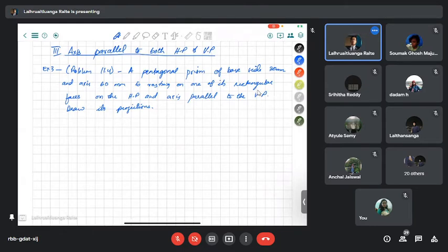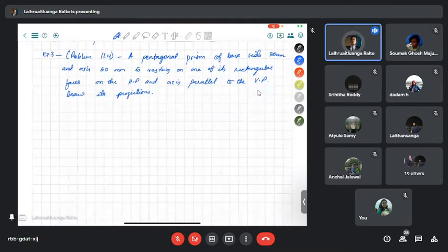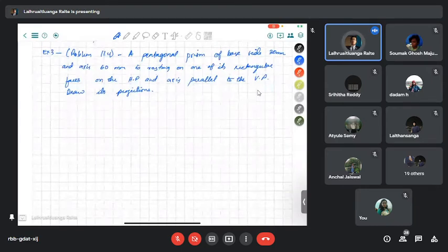Okay. So here we have a condition wherein the axis of that prism is parallel to the VP, and when it is parallel to the VP, it is perpendicular to the profile plane. So that is why we need a profile plane for this particular drafting. The profile plane is where the profile of this solid is going to be projected, which will be the pentagon.